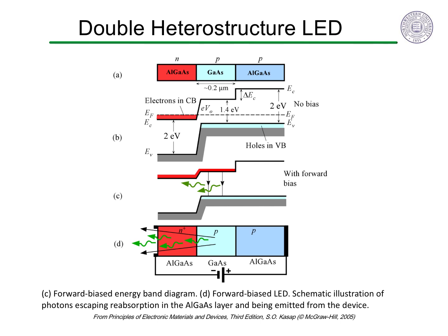loss. The larger band gap is also a confining layer, as it helps contain the injected electrons in the active layer until they recombine. Notice the difference in band gap appears mostly as a conduction band offset at the p-type gallium arsenide aluminum gallium arsenide interface, which acts as a barrier for electrons, keeping them in the active region.